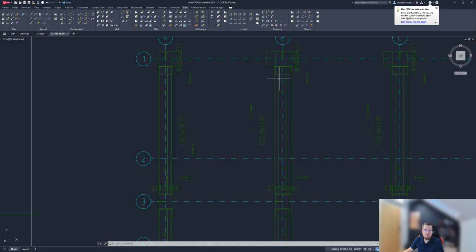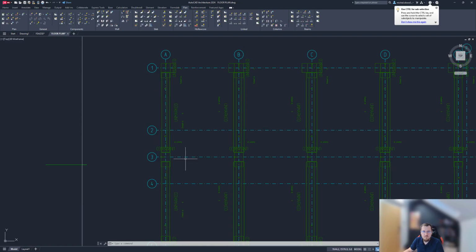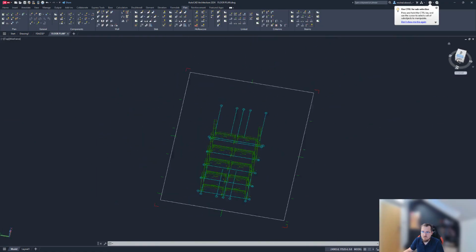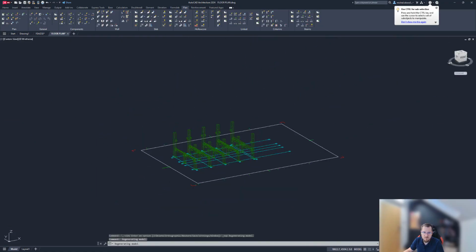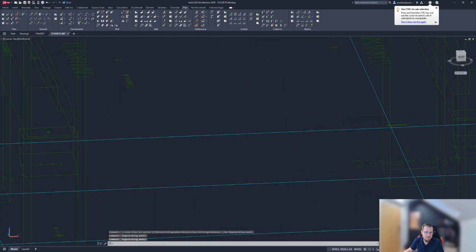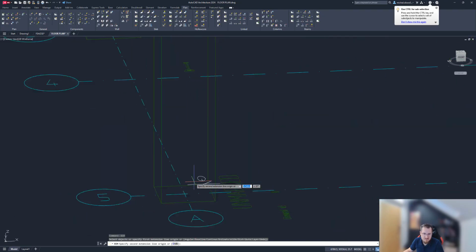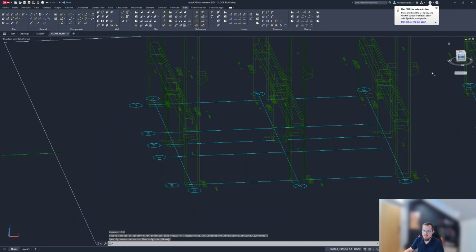We're going to use hollow cores, and we're going to support those hollow cores on the ledges that we've created here. Now, I'm just going to quickly verify the level that I'm at. Everything should be perfectly defined for the project, of course, because I prepare myself for those presentations, but it isn't always the case that it works.